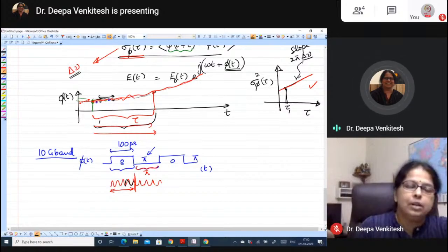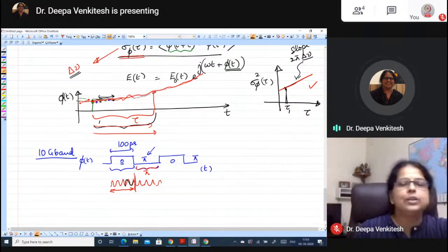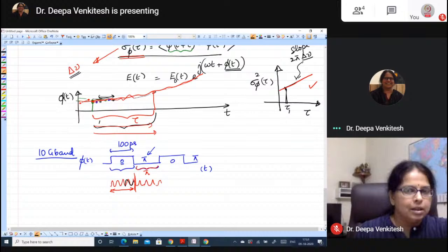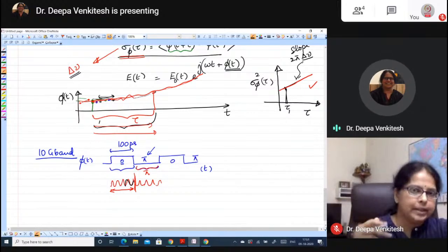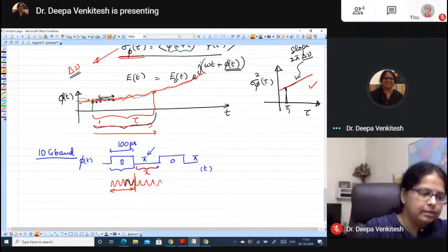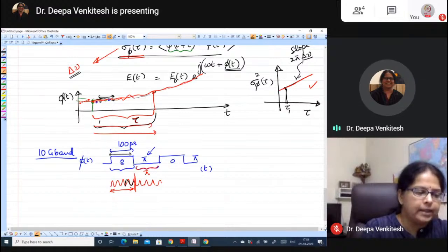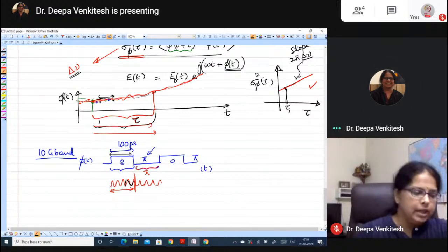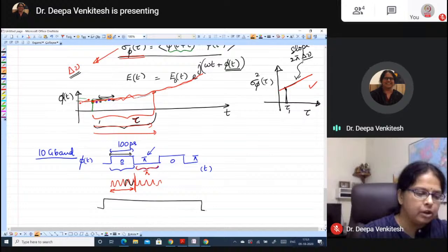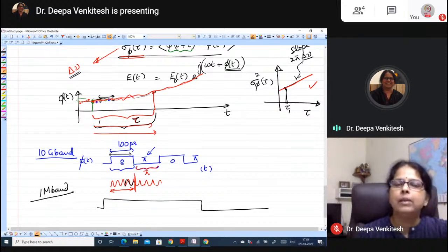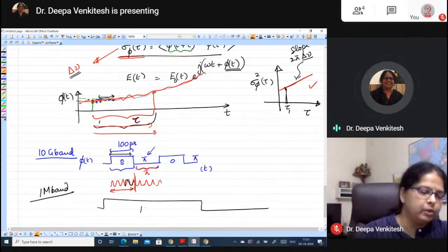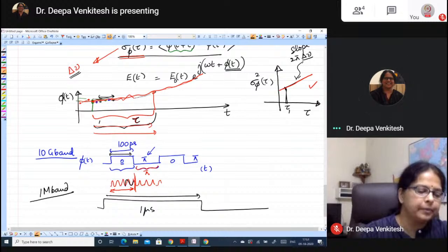It's not listening to the modulating signal, right? That's not something that I want. So what is the connection to baud rate? It's like this, the symbol duration is now acting like this tau. If my symbol duration becomes longer and longer, instead of 1 gigabaud, let's say I'm doing 1 megabaud modulation, right? Now 1 megabaud would correspond to 1 microsecond duration.